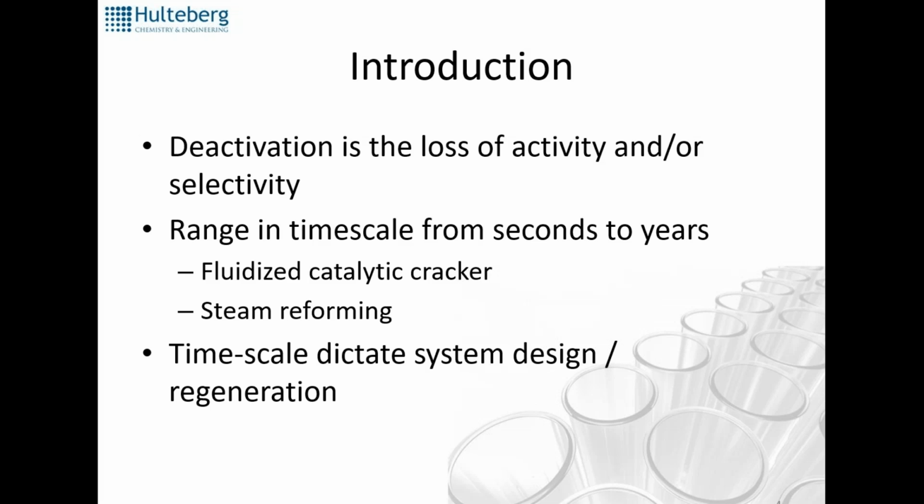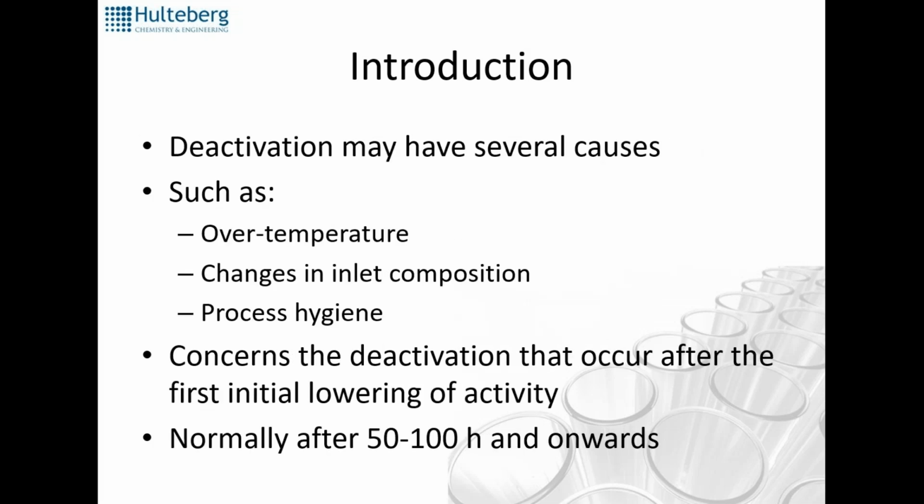So if you have very quick deactivation with carbon buildup, for instance, you need to replace the catalyst rapidly, then fluidized catalysts or fluidized reactors are more suitable. For catalysts that do not deactivate rapidly, fixed bed is the most common one. Deactivation can have many different causes.